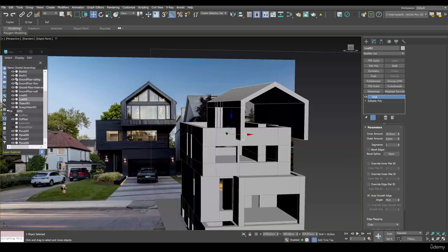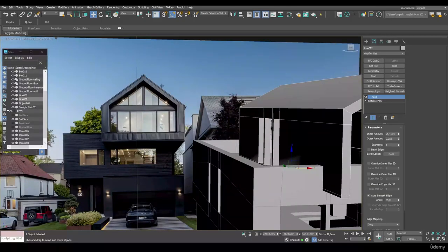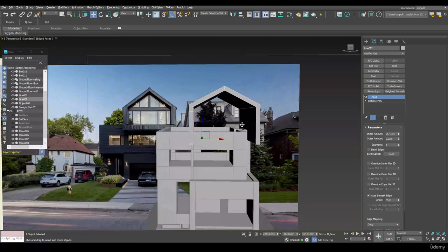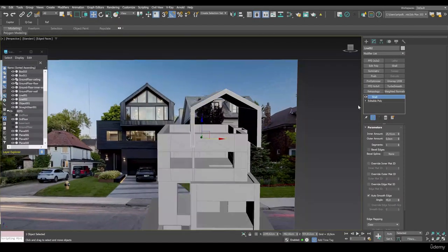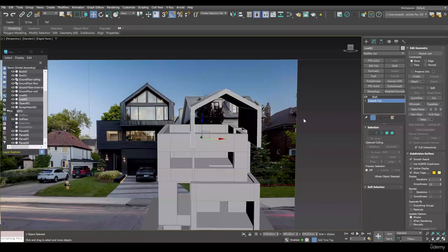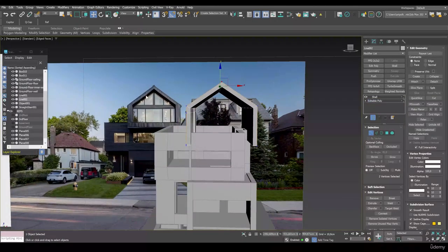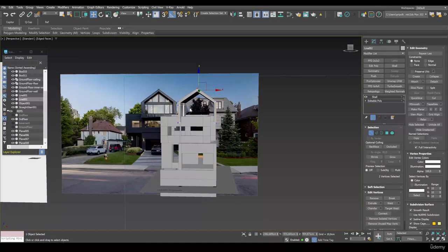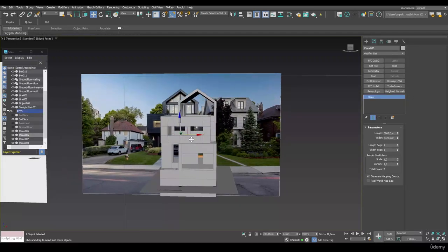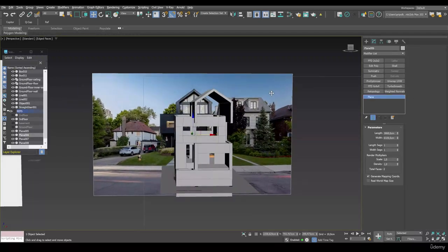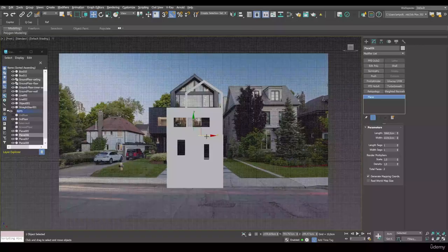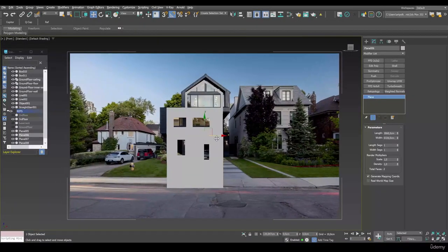And we'll adjust the remaining parts manually, and that's why I set only the thinnest part. And the shape is also what's interesting to me at the moment. So this point that we've made manually corresponds to reality, this corner of the roof slope. And I can move it here in the front view.